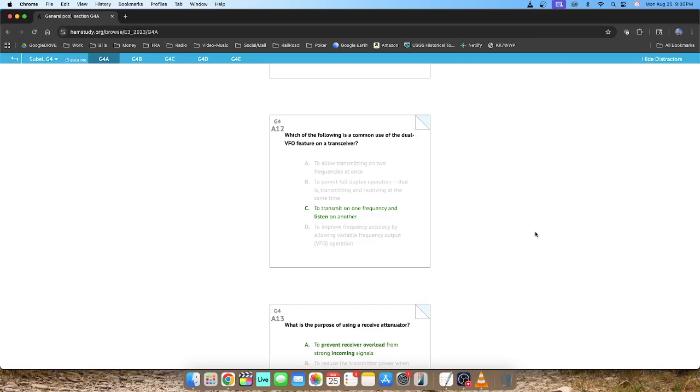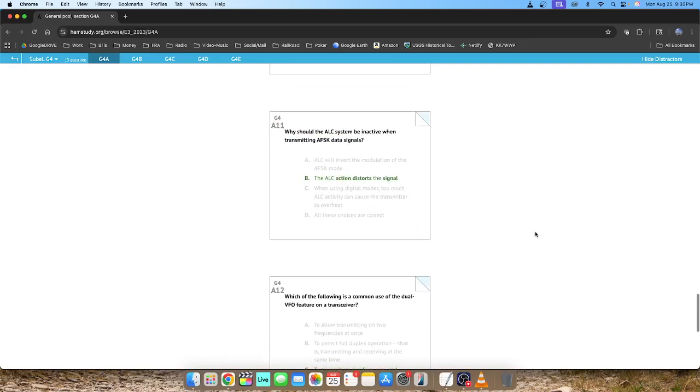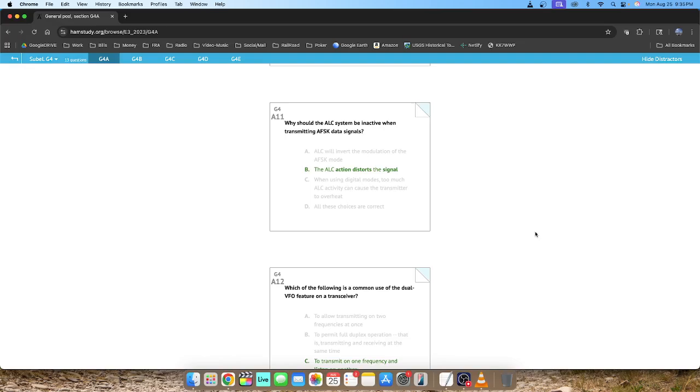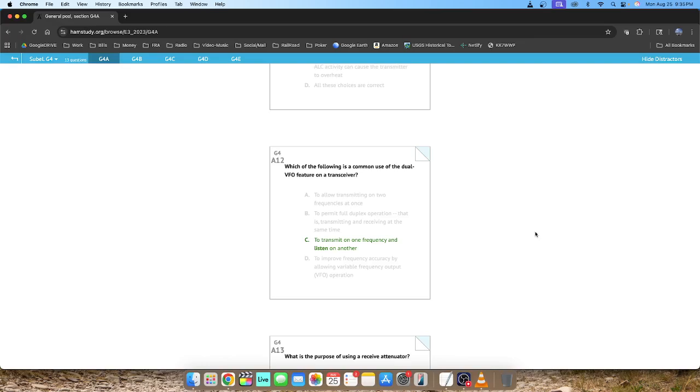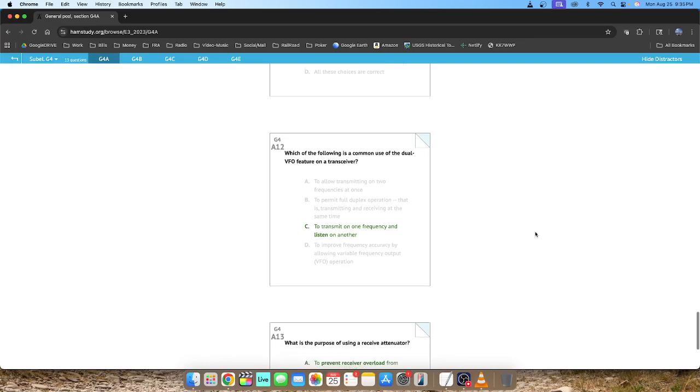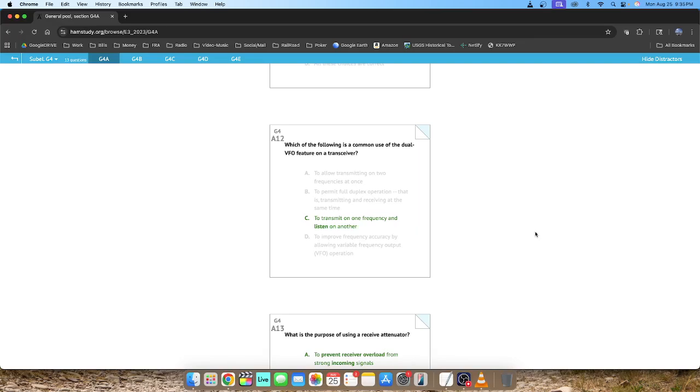Those audio tones are then fed into the radio's microphone input or another audio input, and the radio transmits those tones. On the receiving end, those tones are decoded back into digital data. So it's a pretty common way to do things like RTTY, PSK31, and other digital modes. It's all about using audio tones to carry your digital information over the air.